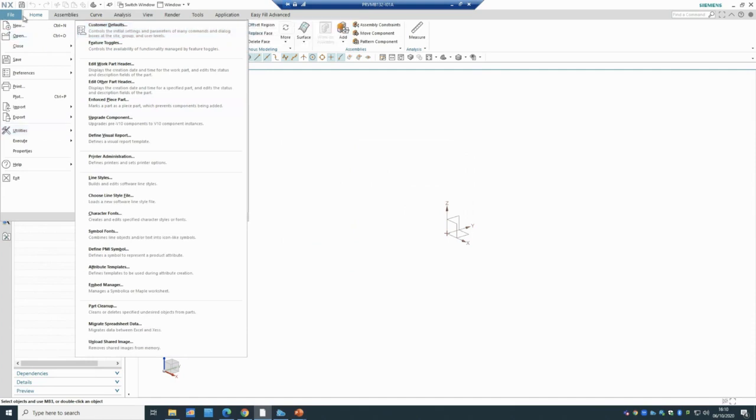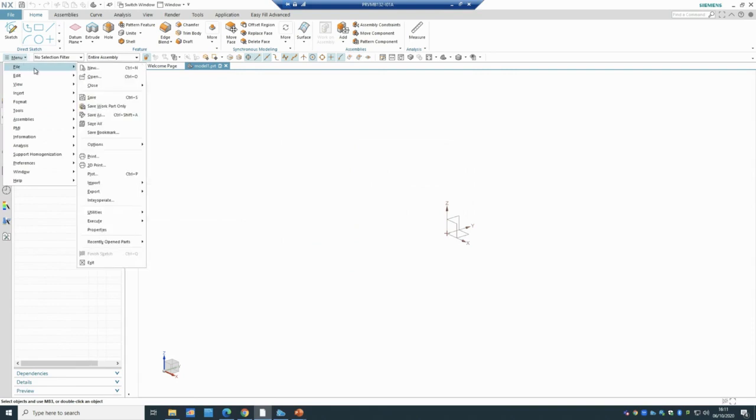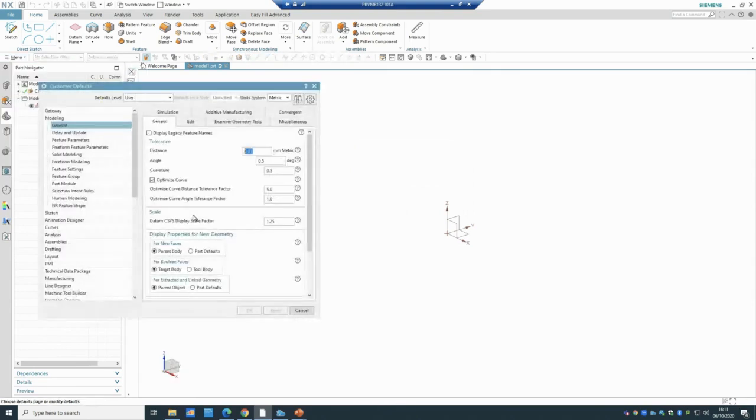Or, as I mentioned, there are different ways in the software you can use. In terms of interface, you can go to the menu, File, and then go to the utilities and also the custom defaults. Once you're in the custom default, the easy way of doing that, you would be able to change your unit system from the metric to the English.